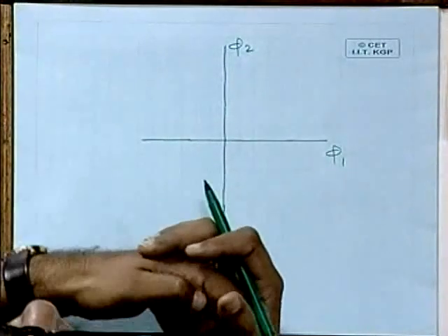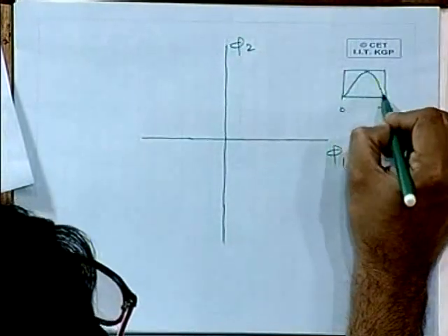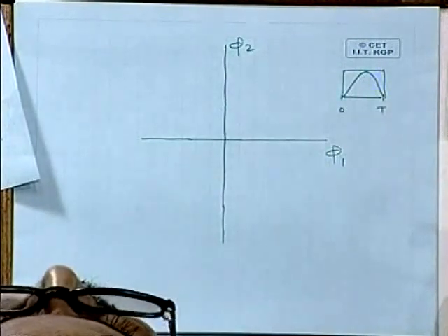So you said that looking at the signal space, you will be able to say what modulation scheme we will use. The scheme, yes, but I won't be able to tell you the exact signal shape against time, because I have never said that this signal vector S1 represents only a special kind of signal waveform. A very simple example: if this is my time duration 0 to t, whether the signal is like this or like this, I cannot say. If both of them have the same energy, then both of them may map onto the same point in the signal space.